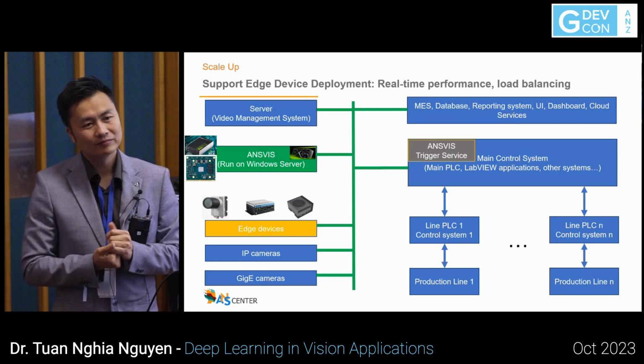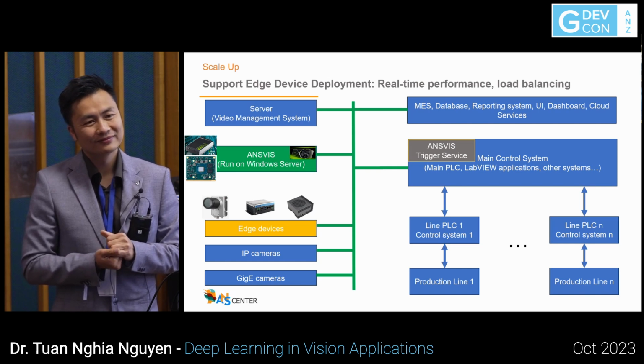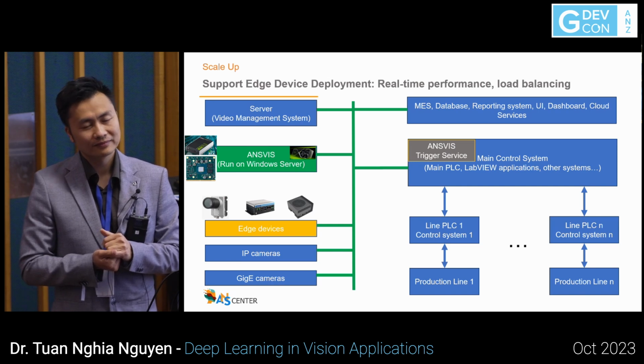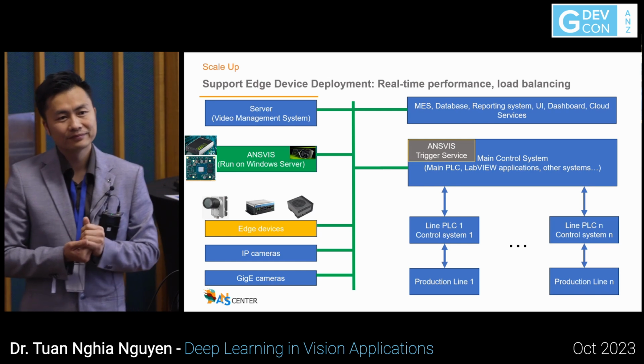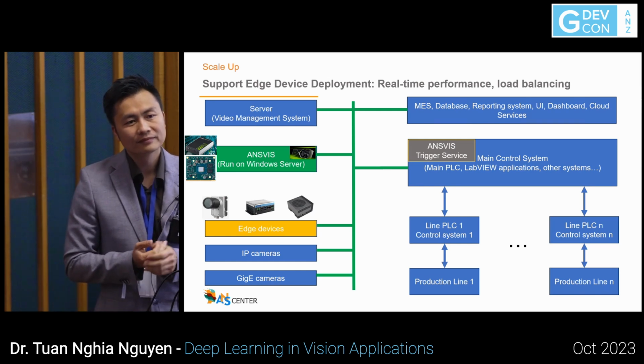Part average testing basically says, and I saw these beer boxes going on the conveyor belts, well done, part average testing works like this. This is what I'm seeing. This is what's normal. So I'm going to accept everything that looks normal. But anything that doesn't look like this batch, I'm going to reject it, even if it looked like a prior batch. Because what's it doing in there? How did it get there?